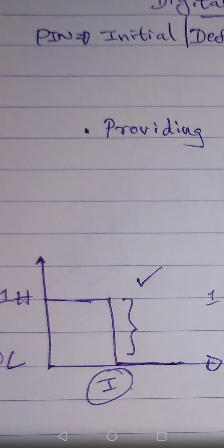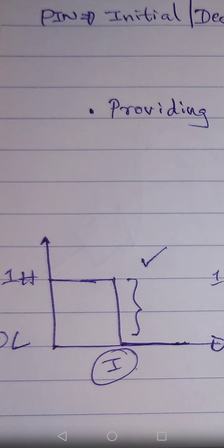Now there are circuits to avoid short circuiting, because high and low cannot meet, but let's say we have such a circuit. Now the ground signal is coming, so this high will fall down to 0. Now we can understand that some input is coming. Let's say you are pressing a switch. The pin was in high state, and when you press the switch, maybe it is connected to ground.